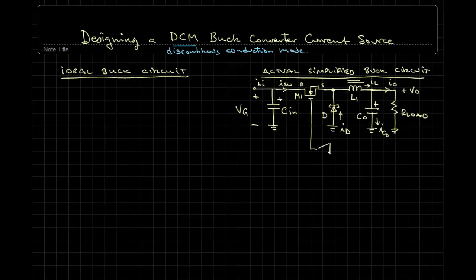Well, and then we need to provide some kind of a gate drive circuit. I will just draw it in a generic form where we'd have some kind of a PWM controller, grounded, with some supply VDD, and it would provide some kind of a periodic pulse, which typically is going to be constant frequency, but it would have variable on time.